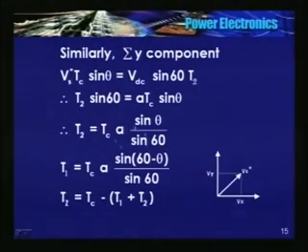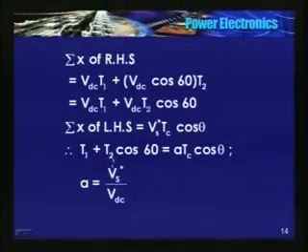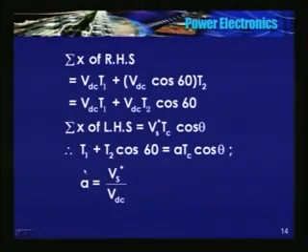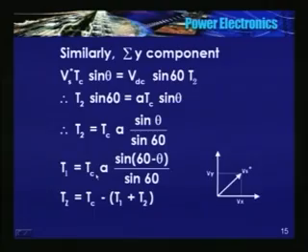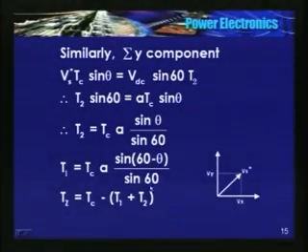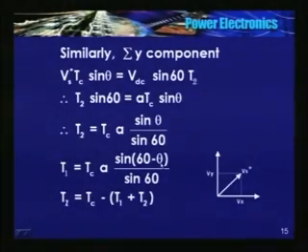I will substitute the value of T2 in this equation and solve for T1. Okay. So I will get another simple equation. T1 is equal to Tc into A sin (60 minus theta) divided by sin 60. What is theta? Theta is the position of the space vector in the xy plane.